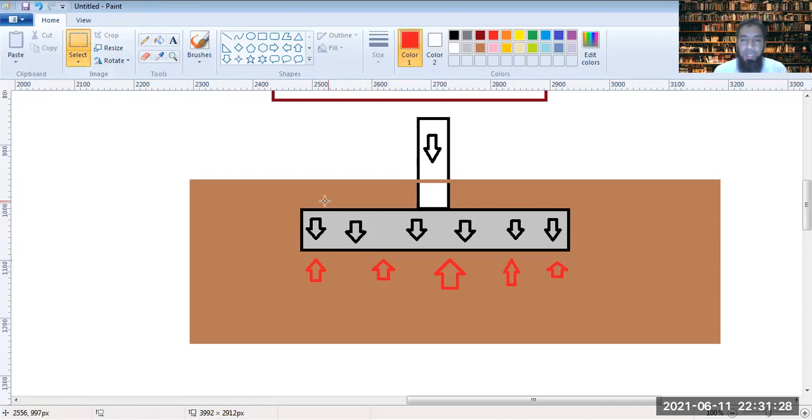Because this footing is embedded in the soil, we would normally assume that the footing is a rigid structural element and does not bend. Thereby the footing distributes the load evenly onto the soil. Due to its property of not bending, it's somewhat like a steel plate: although you apply the load, the steel plate is quite thick and does not bend.